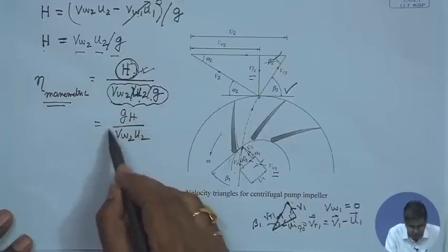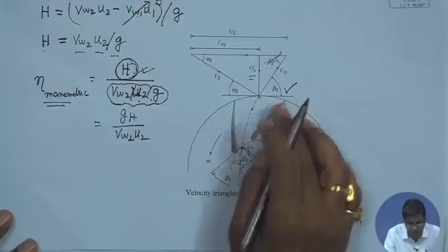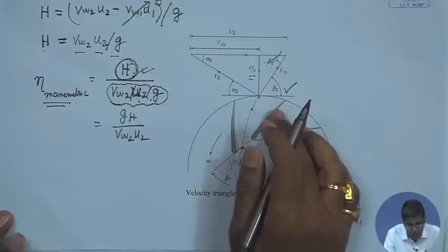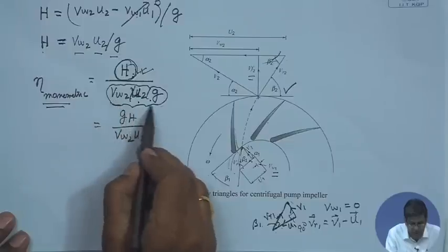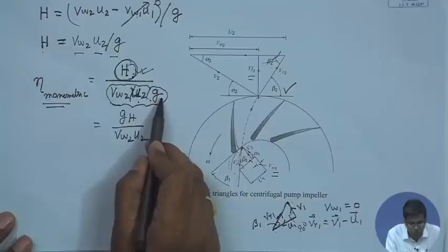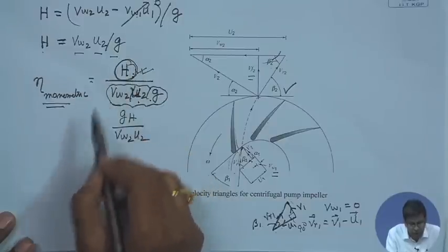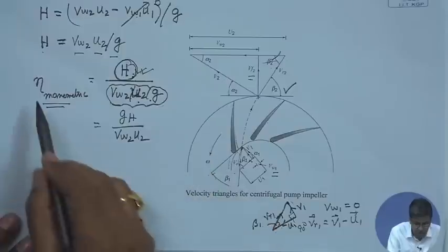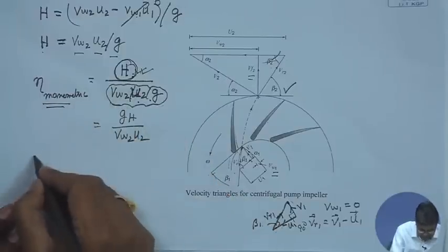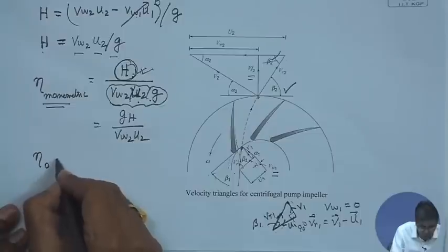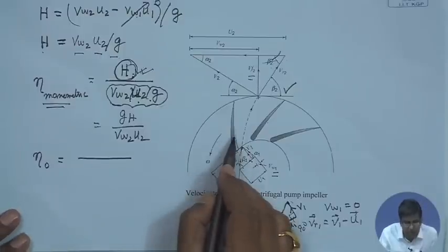So, this manometric efficiency takes into consideration the viscous losses, that is the fluid friction. It is the discrepancy between the head given to the fluid by the rotor and the head developed by the fluid while flowing through the pump. So, this is defined as manometric efficiency. Then another efficiency, as you know, eta overall, is defined as follows, how the overall efficiency is defined.